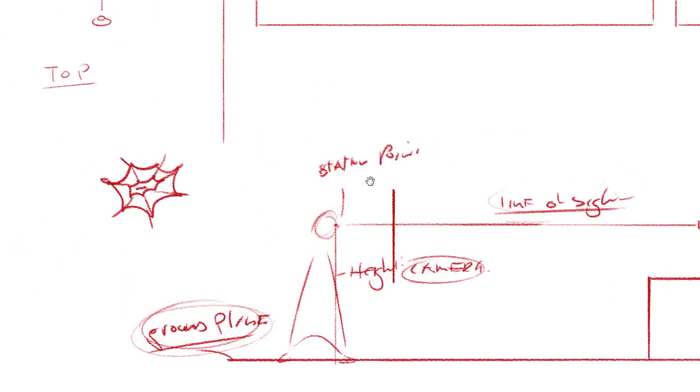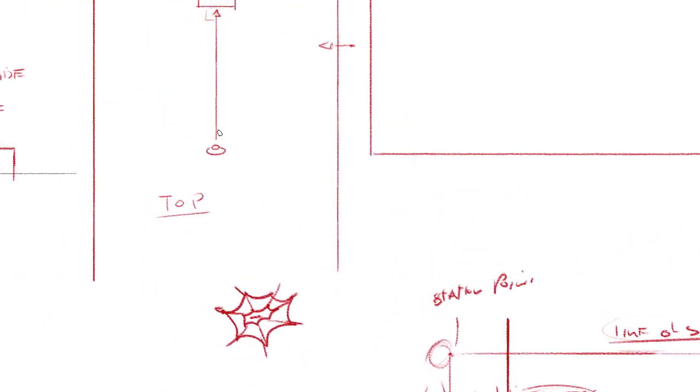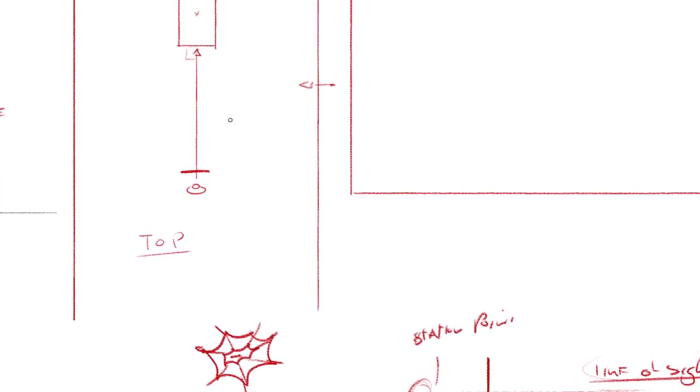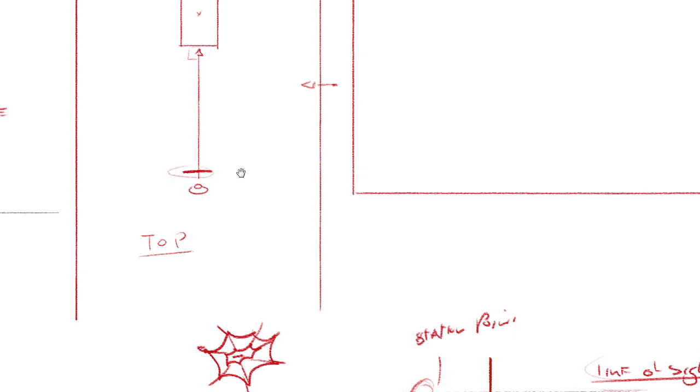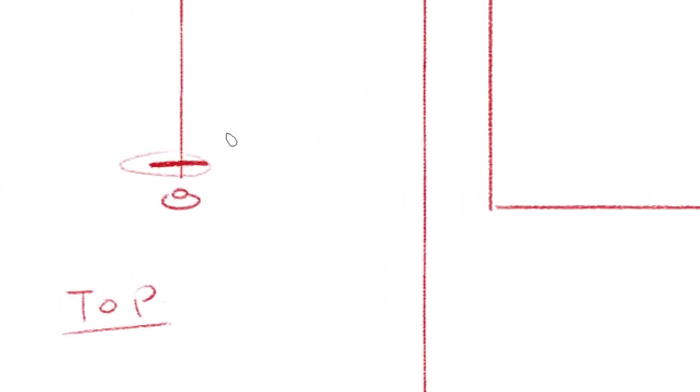Okay, so now let's add our picture plane here. The picture plane is usually, if you think about a piece of glass in front of you, and you would look through the glass, and let's say you're looking at a garden or a building or something, and when you start to draw on the glass the outlines of what you see through it, that is called perspective drawing. So the picture plane is actually the place where the image gets recorded.